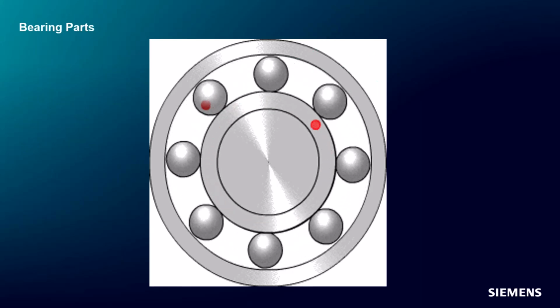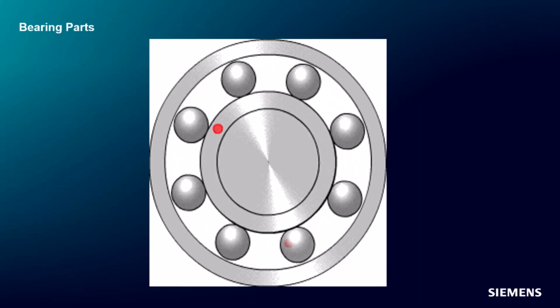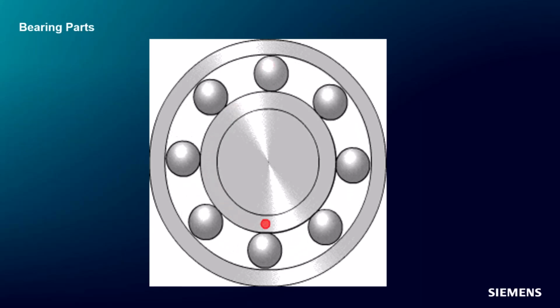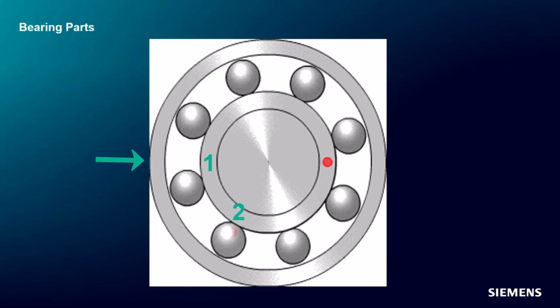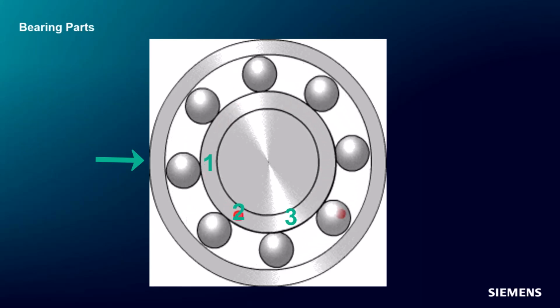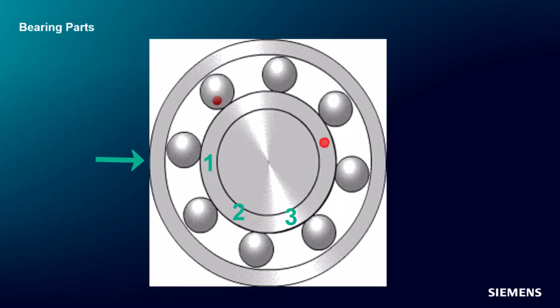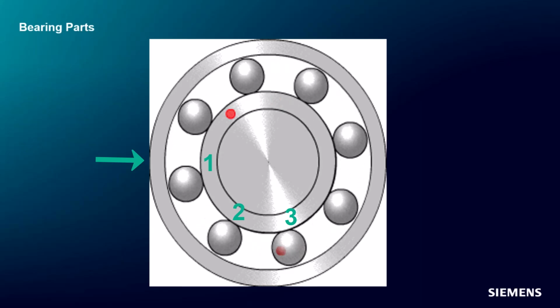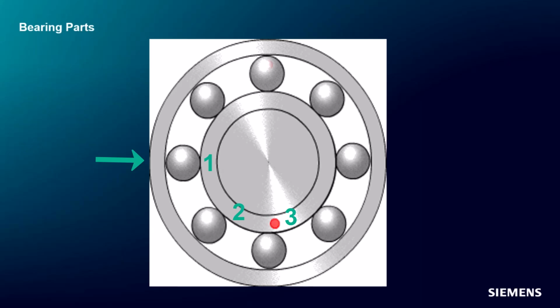The number of times it hits the inner race will count up because you can actually have a different frequency as the bearing passes over the inner race and the outer race. All right, they're about to line up. 1, 2, 3. It hit about 3 times when that inner shaft went around one rotation. Did you see that? And that has nothing to do with 8. Would you agree with that?